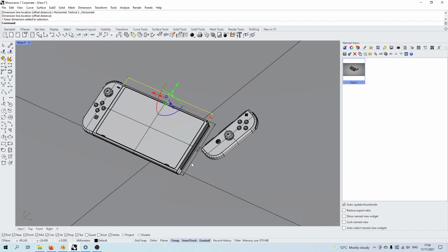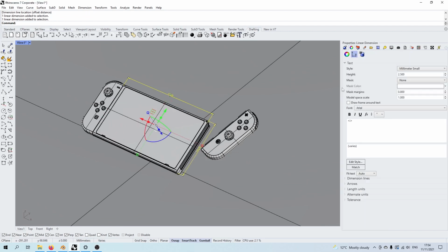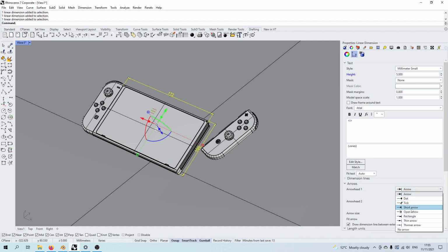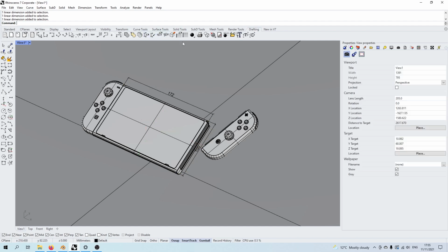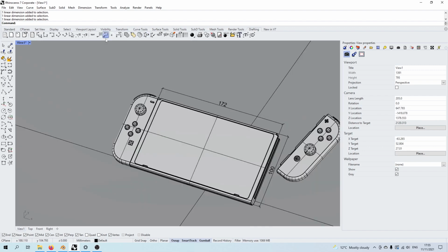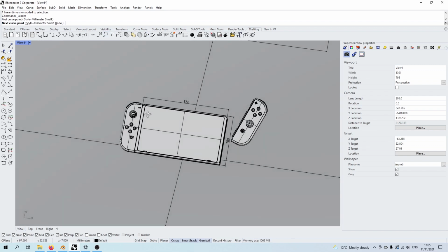We can round the number by changing its properties. Go into the property tab, length unit, linear resolution, and move to 1. We can also change the height of the text, but also the arrows. We can even add a comment pointing towards something on your model.